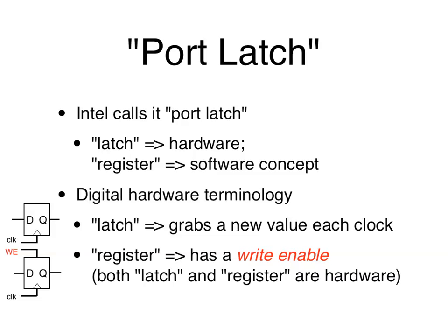So what's that? Well, strictly speaking, in digital logic anyway, a latch refers to a D flip-flop that grabs a new value every clock. Whereas a register refers to a D flip-flop with a write enable. Does that make sense? And if you have done any kind of two-phase clock design, digital circuits, then you know, right?